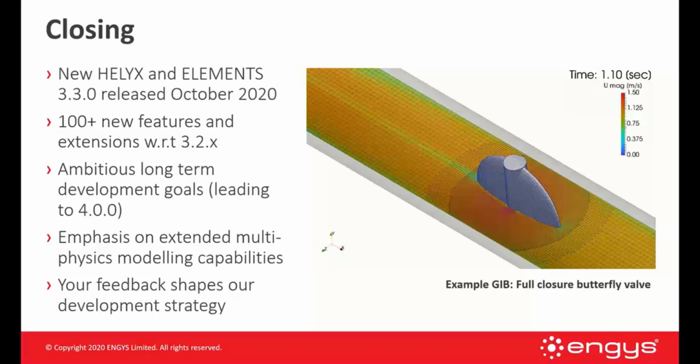Gotcha. And I know that it's written in Python, so you're able to turn things into functions, pass variables to these functions that drive case creation and embed loops to loop through things. So you can adjust a journal to extend the capability. Absolutely. If you are familiar with Python, it's very flexible, and you can take advantage of the Python functionalities and extend to the libraries available in Python and all the packages.